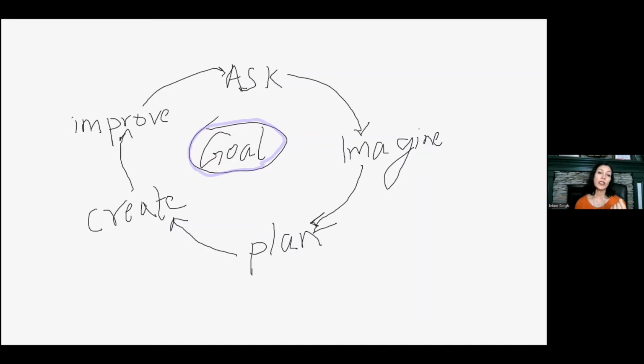One of the biggest issues that we see, especially with this car project, is that you have the axle. So this is the skewer, right? That skewer, and then they cut out their wheels, which are also paper in this particular EDP, and they stick it to both the sides, right? And those are the wheels. The problem happens if they stick the skewer directly to the cardboard, the cardstock, the piece of paper. Now this axle cannot really move. It's not really rotating, right? Because they have taped it to the cardstock. So now the wheels are not going to rotate freely. And this is one of the main issues we see most of the time with these designs.